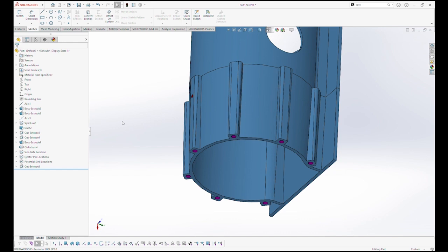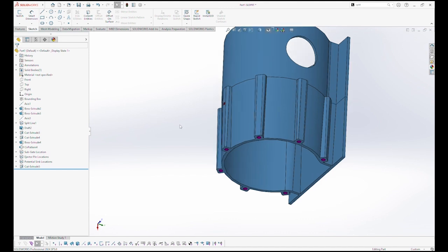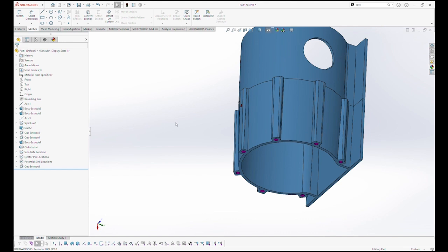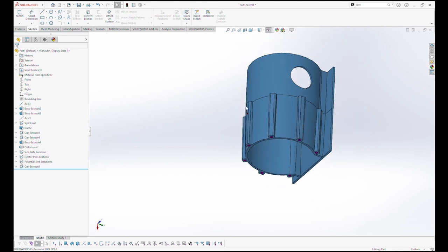If you're using 15 thousandths ejector pins as part of your design plan, then you'll have to have more. You certainly wouldn't want to try to push this part out with 3 ejector pins. The higher the number of ejector pins at 15 thousandths, the better. But if, let's say, your part would allow a 60 thousandths ejector pin in 4 corners and it could equally lift that thing out, and you asked me which one you'd go with, 15 thousandths at 7 or 60 thousandths with 4, I would certainly pick the 60 thousandths with 4, as long as it can equally lift it out.